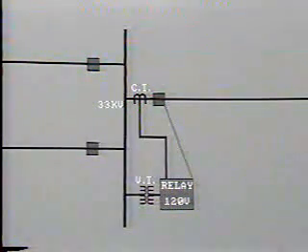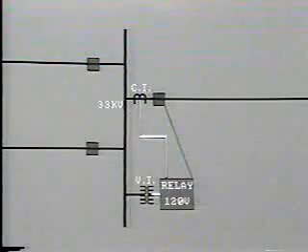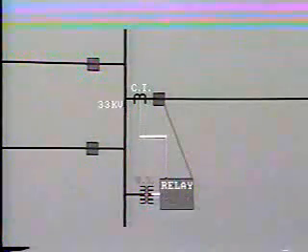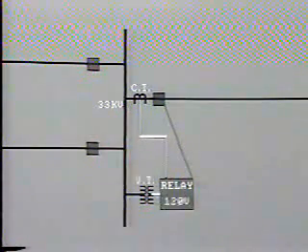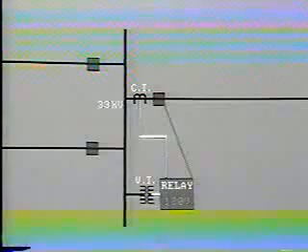This circuit shows the elements of a very basic protection scheme. The inputs to the relays are provided by current and voltage. The voltage is measured by a voltage transformer connected to the bus, which may be at, say, 33 kV. The secondary side of the voltage transformer, or potential transformer as they are often called, delivers 120 volts to the relay. This voltage will, of course, rise or fall in proportion to variations in the bus voltage, so it will represent the actual bus voltage to the relay.